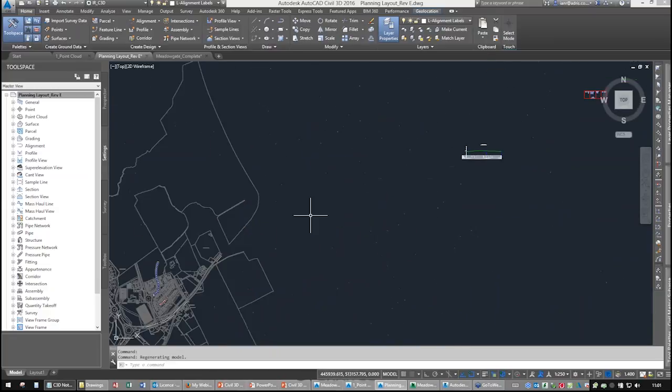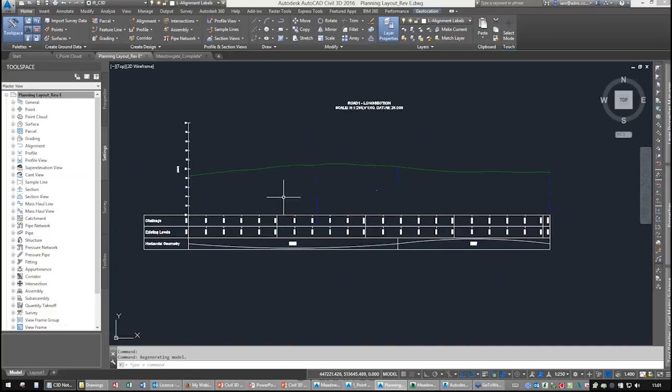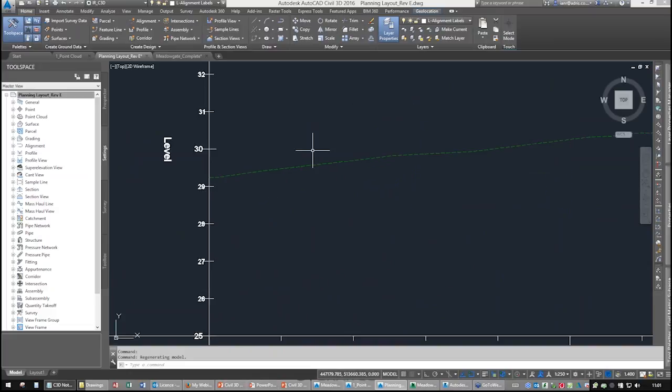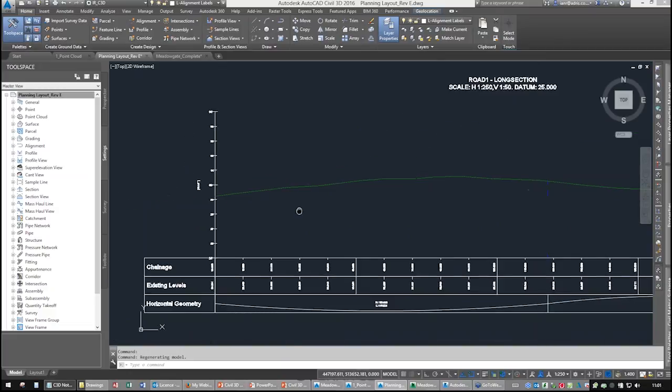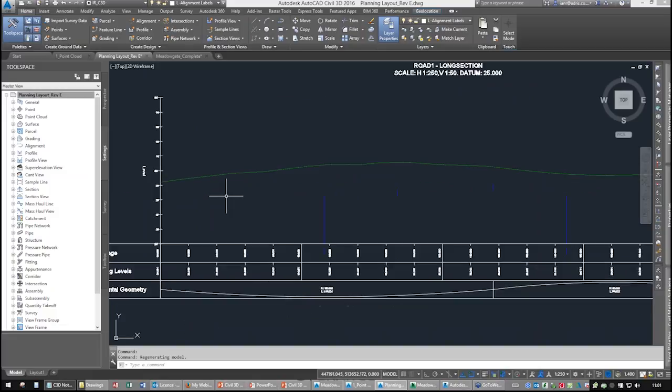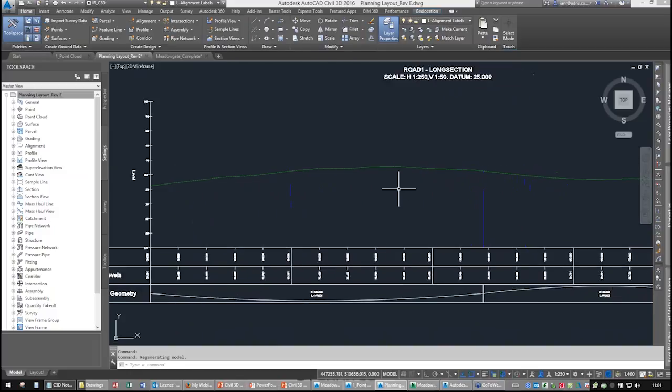Okay, so back to our profile. So in our profile, we have our horizontal design. What we need to now do, as I say, if we start driving on that, it's going to spill our tea. We're going to design our vertical on there now. We want it pretty close to this, and again, you can use best fit on this line if you want, and it will actually create a nice curve best fit on there.